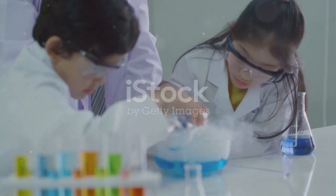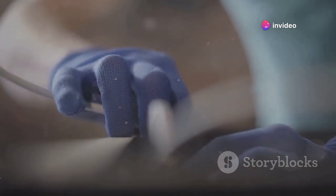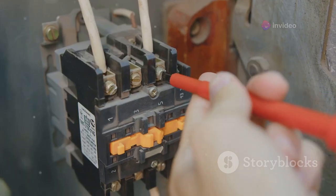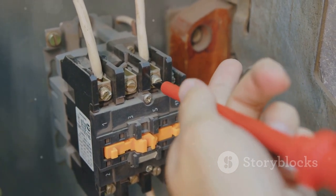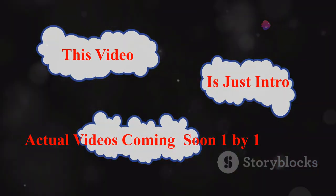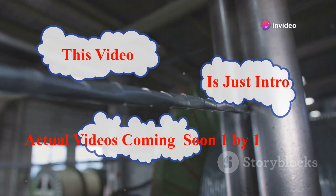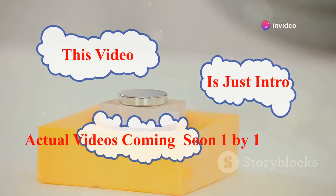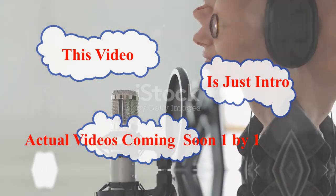When conducting these experiments, it's important to keep safety in mind. Always use insulated wires and handle magnets with care to avoid pinching your fingers. If you're using electrical components, make sure they are properly rated for the voltages and currents you are working with. As for expected outcomes, you should see a measurable current in the wire when the magnet moves through the coil. This demonstrates the fundamental principle of electromagnetic induction.